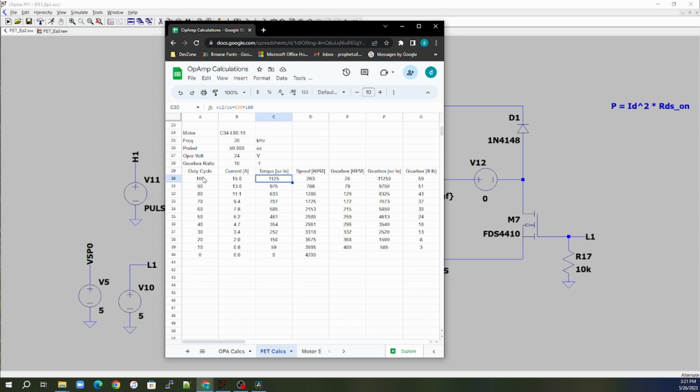So what you do is you add a gearbox. And then we put the gearbox on. I'm just choosing a 10-to-1 gearbox. So with this gearbox, we can convert the speed into torque. So when we take the gearbox into account of 10-to-1, we'll take the speed and we will drop it by 10. But at the same time, we convert the decrease in speed of 10 and we convert it into torque. So we can multiply our torque by 10.